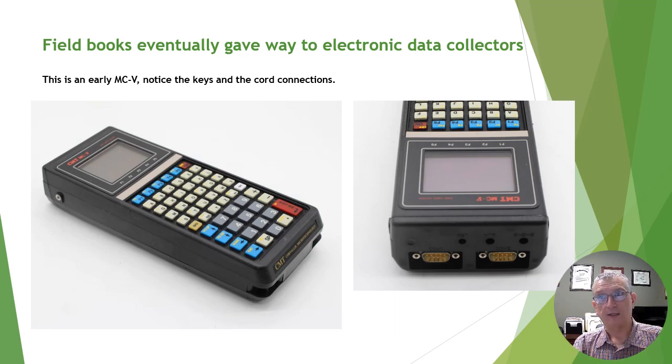Some would even get a DOT crew to come by and set up and turn it with a T1, a theodolite developed for really high precision geodetic survey, to get that angle so that they could check their electronic instruments. And so that was calibrating it. If you knew that the angle was 84°05'05" and you set up an electronic theodolite or total station, you better get really close to that same 84°05'05" or the surveyor would not trust it.